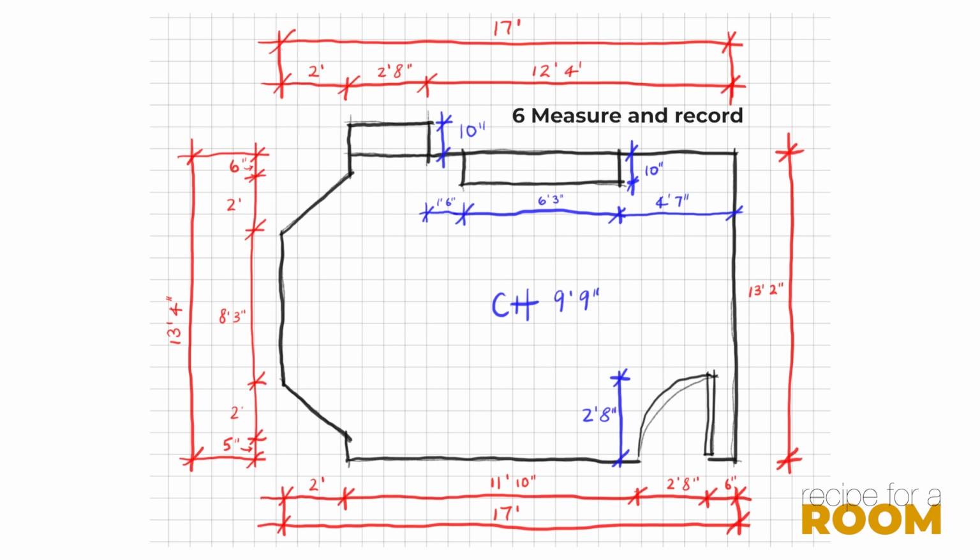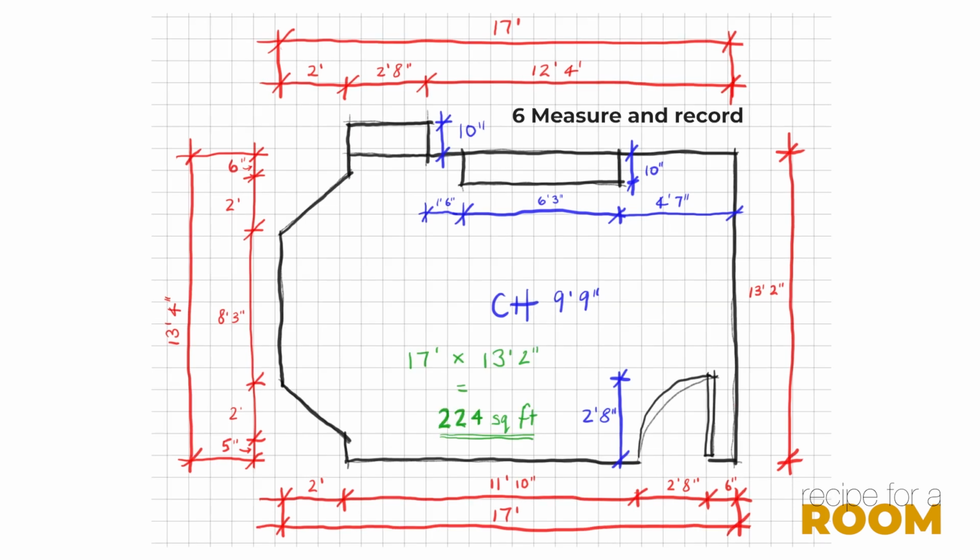So, still on step 6, here's the imperial measurement example. And note that I've also recorded the ceiling height, so that's the dimension shown as CH in the centre of the page. For some uses of plans, so for example if we're making a lighting plan or ordering flooring, it's also helpful to know the overall area of the room, and you can roughly work this out too. I've added this information in green. And here's a quick look again at the metric example.